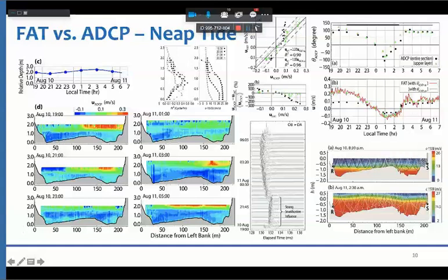of the sound speed. And here we can see that if the source and receiver are not submerged into the salt wedge, then the sound ray is going to be trapped in the upper duct, so it actually measures the high speed flow, and it just neglects the low speed part of the cross section. As a result, it overestimates the water velocity.